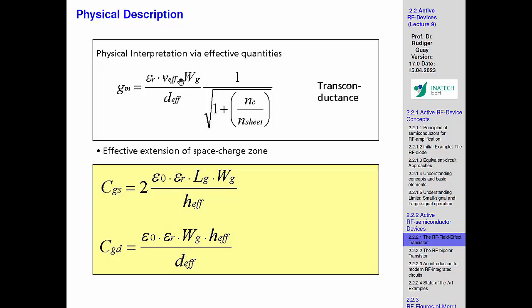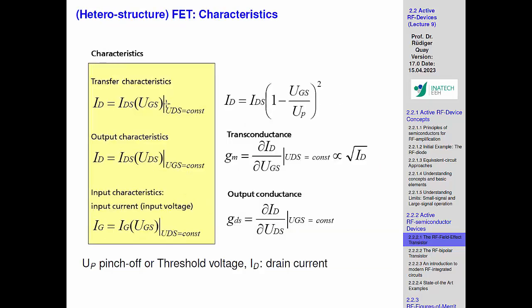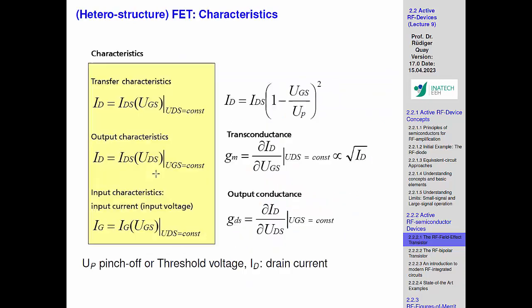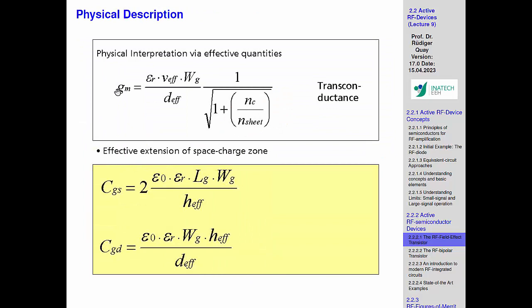The other thing is, two things which we already mentioned, there's the effective distance of the carriers from the gate. Yeah? So I always told you this example. This is not what I mean. I cannot control the people in the back of this room. If they're here, they're closer. And so it is the same as what you know from CMOS, where you have channel separation or oxide thickness. So if the oxide thickness, or here in this case, the distance of these carriers from this gate, gets closer, that also increases your control. So you can control the current better if you're getting closer.